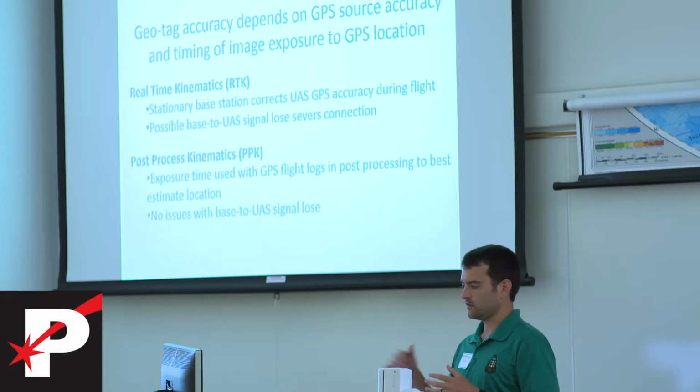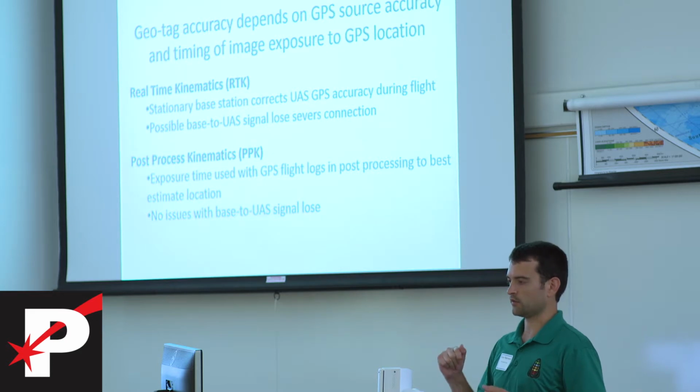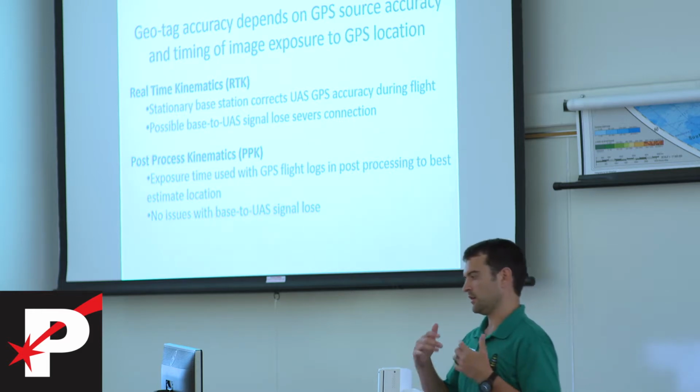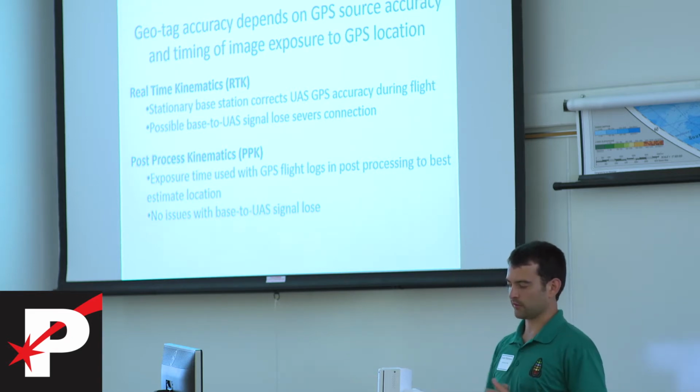There are two technologies that are used, and I'm sure DJI will come out with it, but the other companies that are doing geotagging are using RTK and PPK information if you're trying to do real-time or non-ground-control-point-based corrections to your 3D model, 3D work.